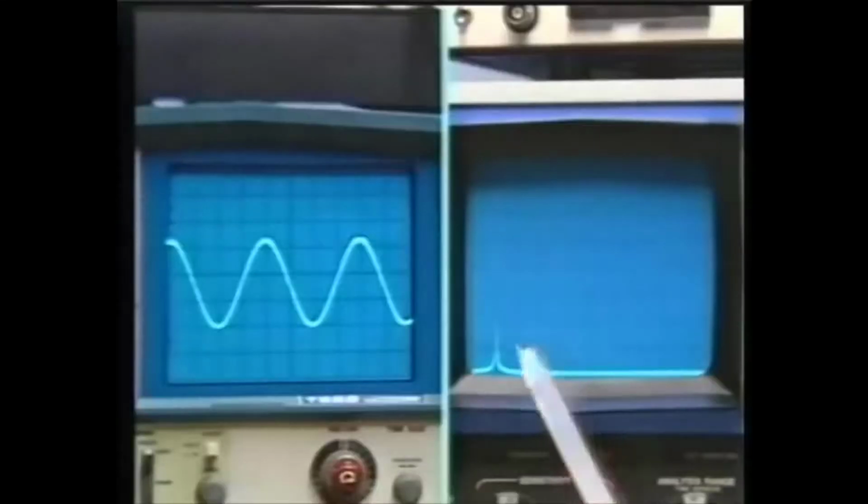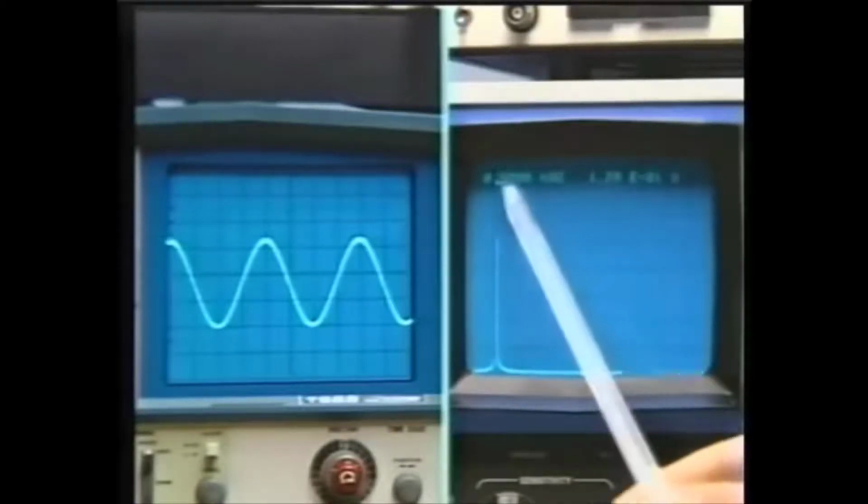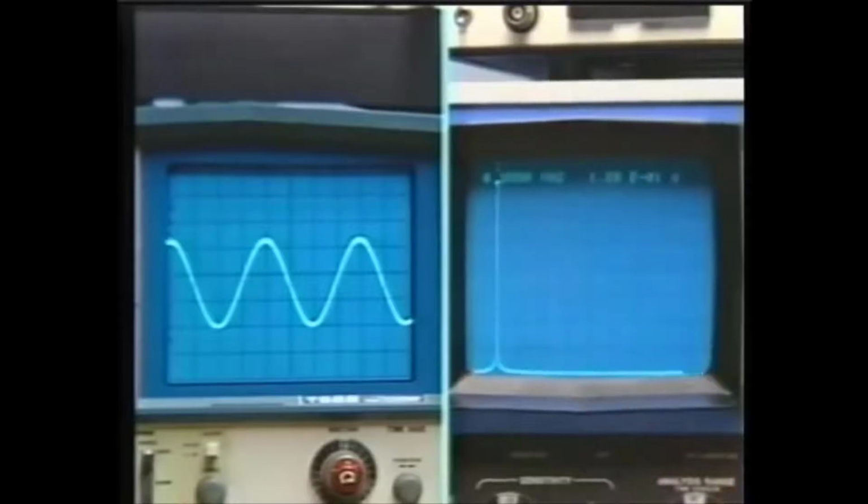We'll look at the square wave through the spectrum analyzer shortly, but first what we have is what we saw before, which is the sine wave, and just to point out again the fact that the sine wave spectrum, of course, is just a single line corresponding to the fundamental frequency. And here we have a frequency scale now that goes from 0 to 5 kilohertz. And this is then the 500 cycle sine wave. In fact, we can flip the cursor on, and I happen to have it positioned correctly, and we see that it's a 500 cycle sine wave.